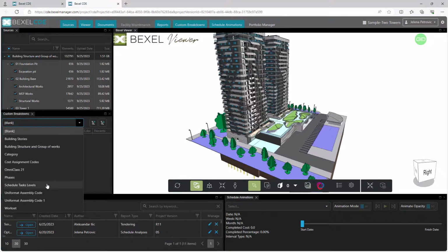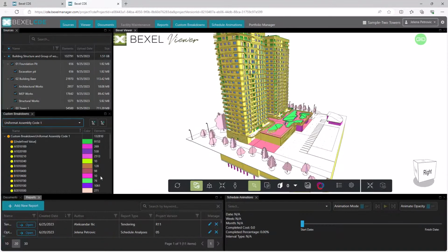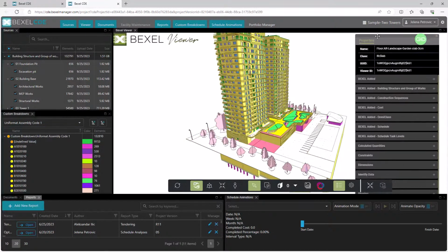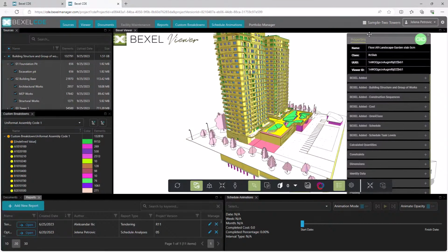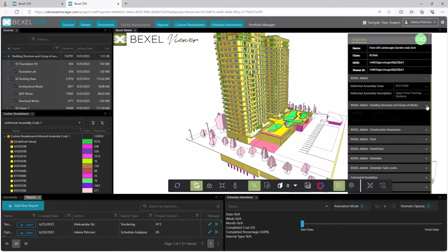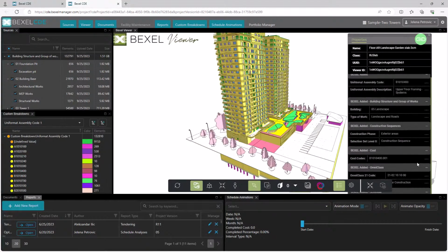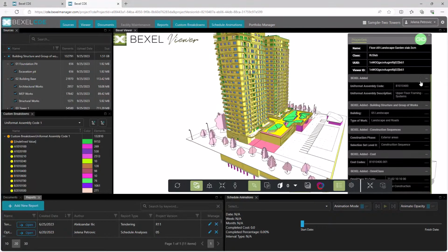To overview element properties, we go to the Inspection Properties command, and Properties Inspection allows us to overview BIM model properties and select BIM model elements using desired properties and their values. Here we can see all properties our enriched BIM model includes.